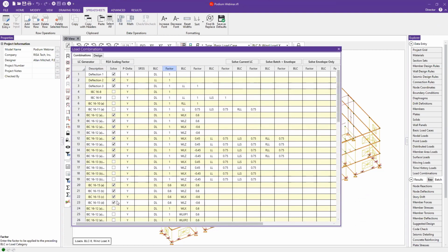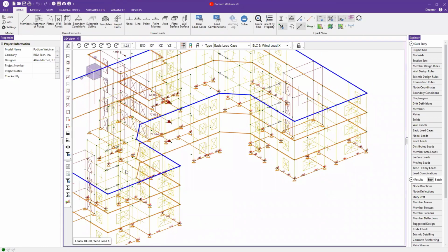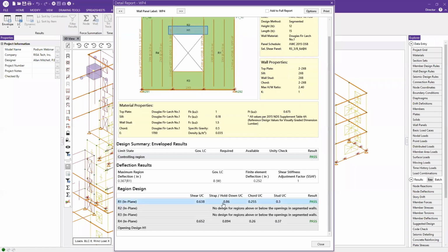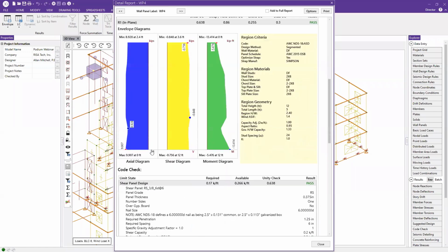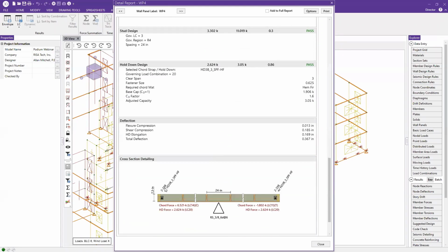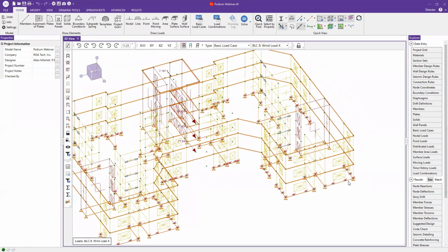I've run just a few of the important ones here to take a look at the results of my structure. So at this point, I'm doing sort of my typical RISA 3D operations. Maybe I'm checking out, say, the detail report for this here shear wall. And I check that everything here is passing. Okay, where are my straps, my hold downs, my moment and shear diagrams. I get whatever detailed information I need from within this detail report. I'm happy with this. Maybe I can print it off to a PDF. And at that point, I've pretty much wrapped up the 3D analysis.